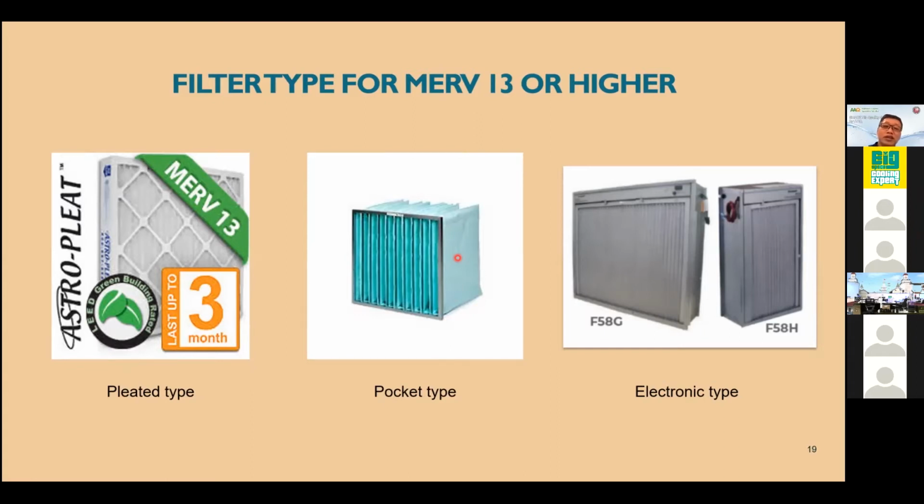But the thing you have to consider is your fan. One thing, the static pressure is not there. Secondly, your ACMV ducting is already done, and now you want to modify it, it's not catered for high static. Your duct will collapse with that kind of static. For your return air, your duct will collapse, and if your fan is not upgraded, you don't have airflow. The supply air is not there.